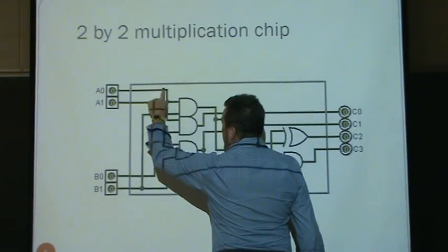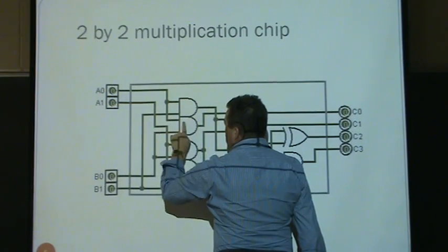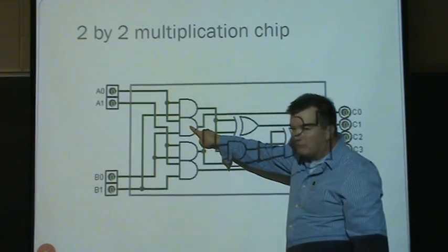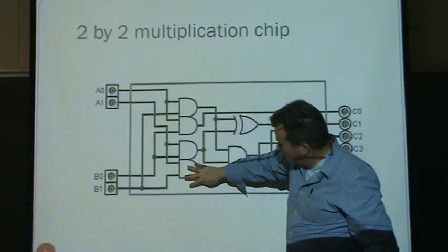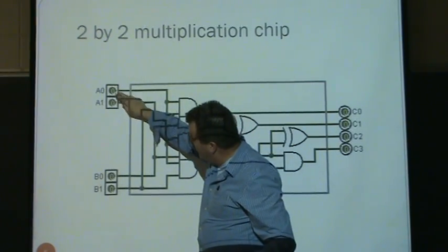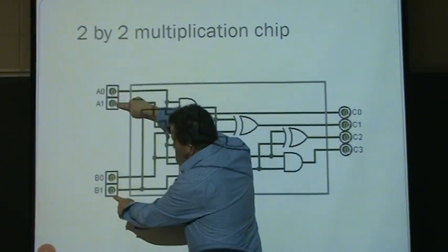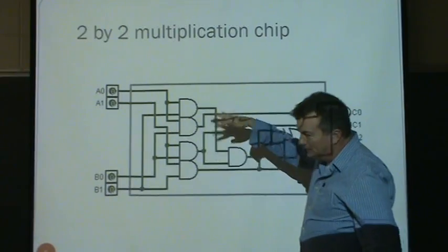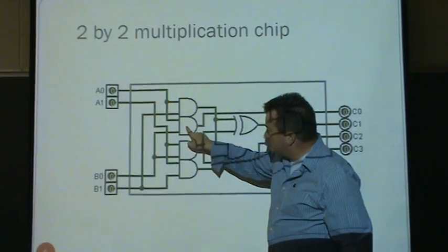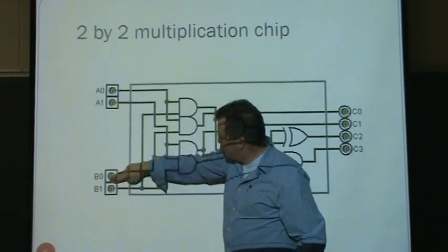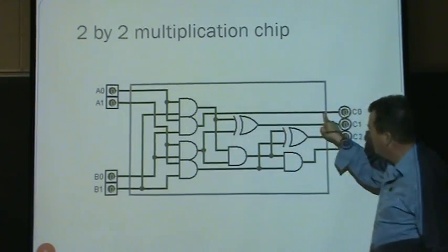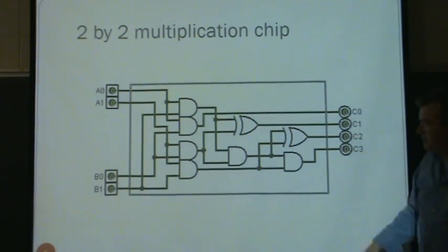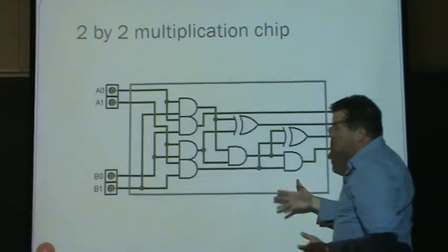So if you look at this circuit, this goes into here, and the lowest bit goes into here. So basically this first row of AND gates is the combination of all the bits. This one and this one, and the second one here and the first, and the second and the second. That's what these are. And it would be kind of good if they did them in order, but they didn't. So this AND gate represents the 2 low order bits are on. So if this is a 1, then the output will be an odd number. If the 2 inputs are both odd, this one will be odd. And then after that, it's just different combinations that would make them turn on.